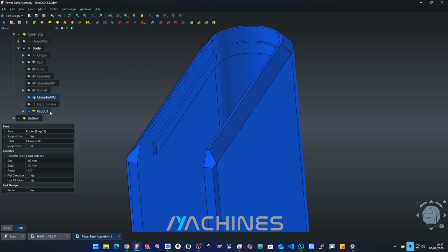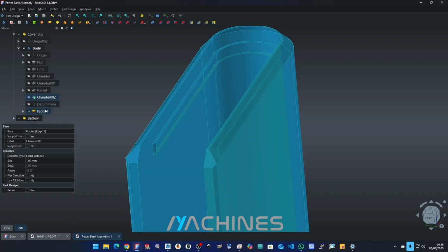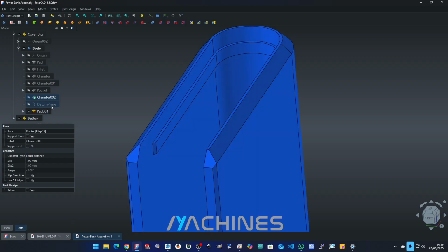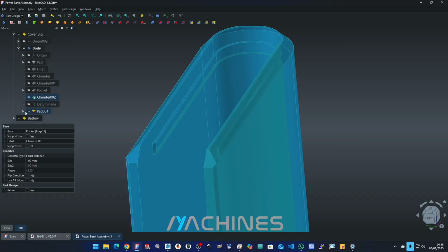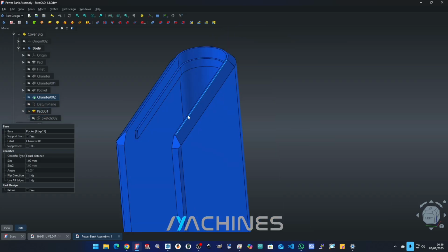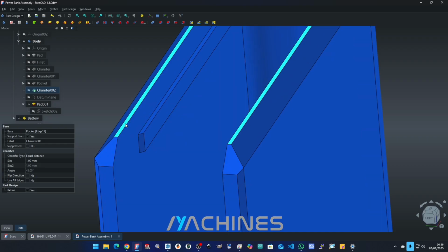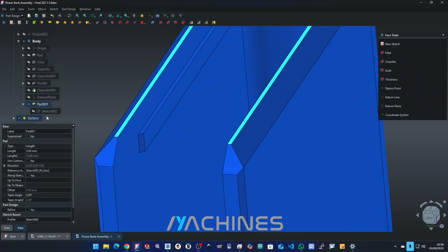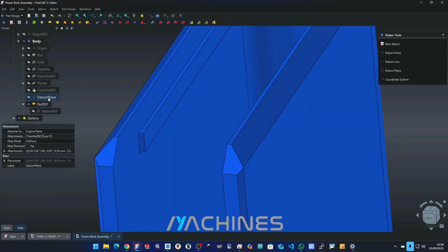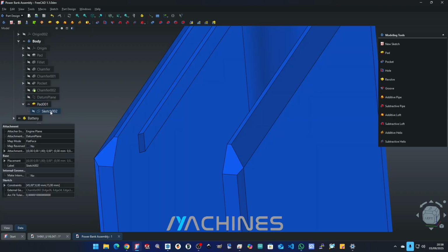Okay, this is one thing I have to do to change the sketch of the path to the datum plane. After I arrange the datum plane up the path, then I can change where the sketch was. So the sketch was in this face, and you click here, and then you make the attachment, this attachment here. You change it.